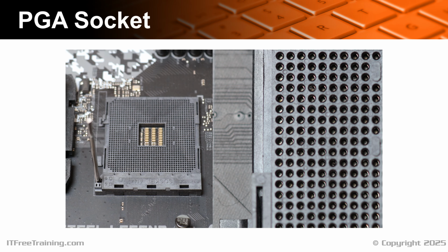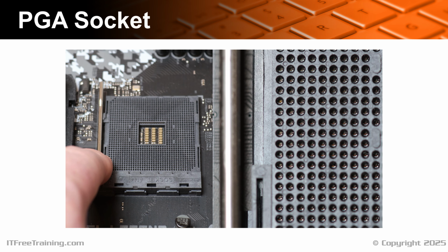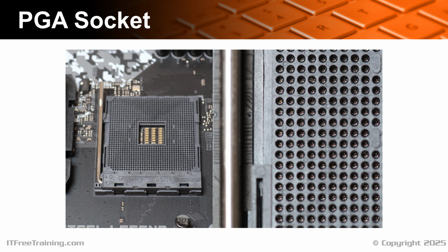It's an older socket with fewer pins, so it's easy to see what is happening. You'll notice that the socket cover has a large number of holes. Under the socket cover are the contact pins. You'll notice that when the lever is pushed downwards, the socket cover moves. The socket cover essentially moves the pins of the CPU so they make contact with the pins below the socket, thus locking them into place.